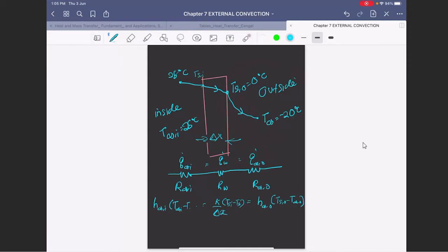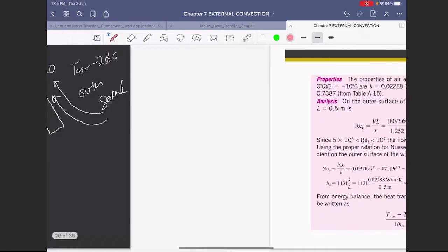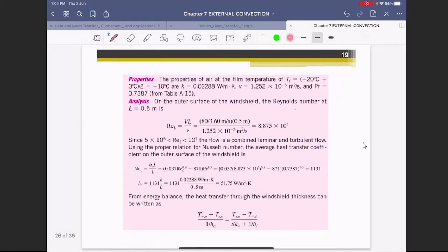Surface in. All of these are similar. Now, our purpose is to determine H for each layer, this one and this one also. But I can find this using this technique, the Nusselt number. Can you see this? Based on this, you obtain your H for the outside air. You know how to get this, right?